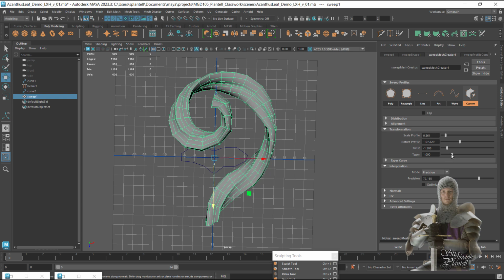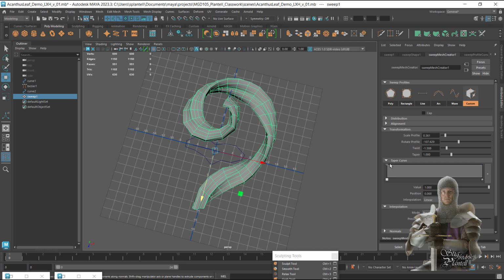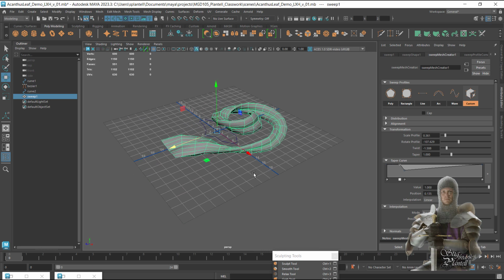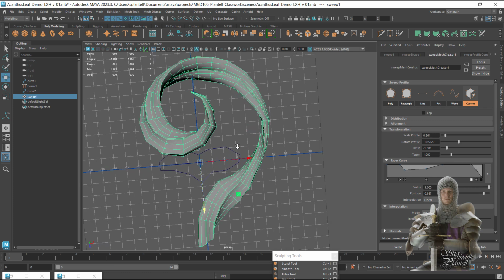I can also taper. If you haven't seen that, you can taper it. Now, I wouldn't taper it all the way down because what I'm finding is there's something cooler: a taper curve. Now, this can edit the profile. I'm going to start with a really fat end, so I'm going to keep that up high. I'm just going to click with my left mouse button. Make a thick edge. Let's just bring it over like that. So everything to that point is large. Then we maybe taper it just a little bit and then swell back up to an end over here that's very full.